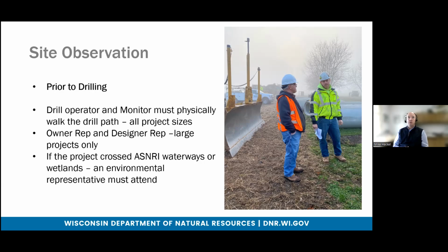The drill operator and the drill path monitor must physically walk the drill path during this meeting for all project sizes. Owner rep and designer rep would only need to be present for large drill path projects. If the project is crossing an anadromous waterway or a wetland, then an environmental representative for the project must also attend this meeting prior to starting.